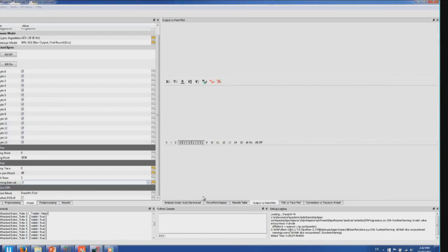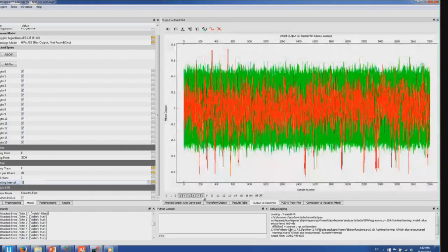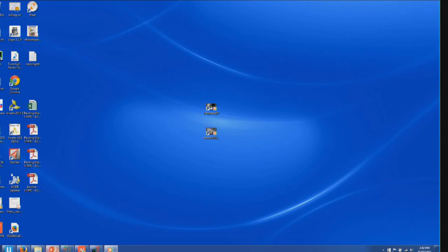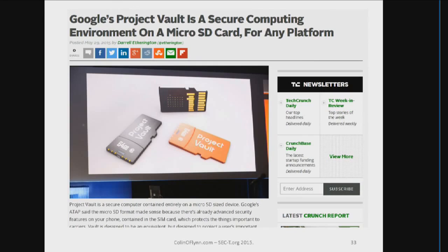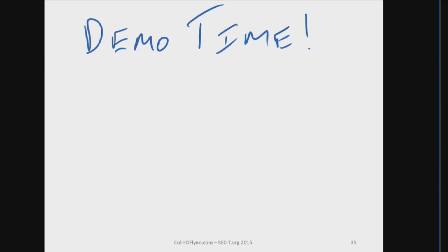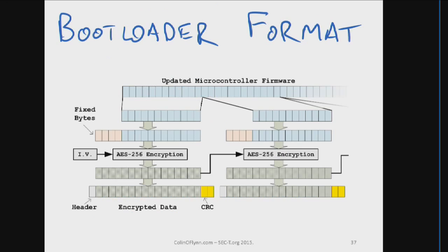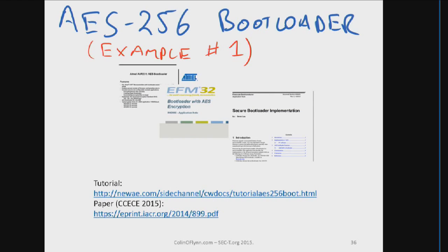And as it goes on, it comes a little slower in redrawing. But you see the same thing, marching on in time. And that's just the for loop inside the C code as it's running. So that's a really basic AES attack. In that case, I have a device programmed that just does AES and returns the results.